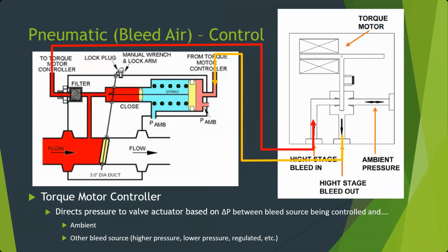In this case, this valve is spring loaded one direction. You can see the big spring there, but then we can adjust how open or closed this butterfly is with some feedback, and provide an input to the torque motor controller, so it's variable and we can make changes to it. It's looking at ambient pressure here. It can also look at downstream pressure.